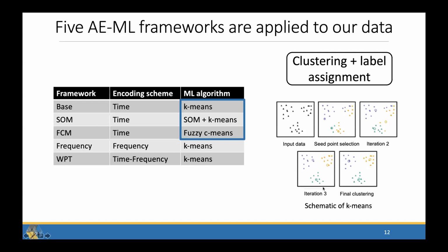That's the general idea. And so we're trying to do this to say, these data points are a fiber break, these are a matrix crack. In the literature, far and away, k-means has been used to do this. It is very robust, and we do use it a lot. What we'll see is it's not a good choice for this particular application.